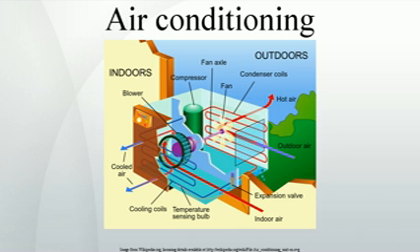PTAC systems are also known as wall-split air conditioning systems or ductless systems. These PTAC systems, which are frequently used in hotels, have two separate units, terminal packages, the evaporative unit on the interior and the condensing unit on the exterior, with tubing passing through the wall and connecting them. This minimizes the interior system footprint and allows each room to be adjusted independently.